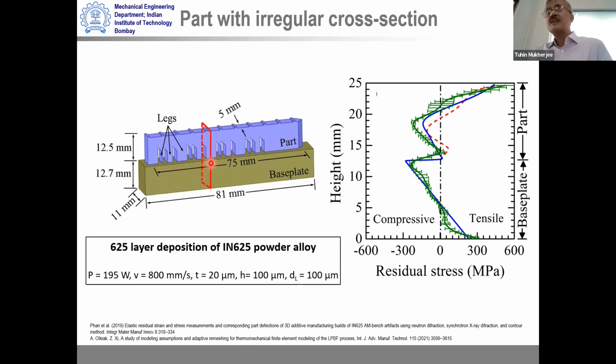And this can be compensated by doing some kind of stiffness adjustment, because the area is less, its stiffness would be less. This can be incorporated in the model. This is already there because we are doing a moment equilibrium, so it will automatically go inside. And there also, as you can see, this analytically computed stress distribution, represented by this blue line, through the thickness along this section, is not very far from the experimentally measured results by contour method and the numerically computed results. Remember this now.